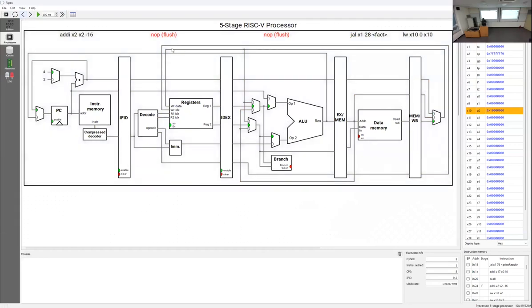We will learn about the control hazard later, but you can find that because of the control hazard by the branch instruction, pipelines are flushed. It means that these pipeline stages are filled with no instruction.